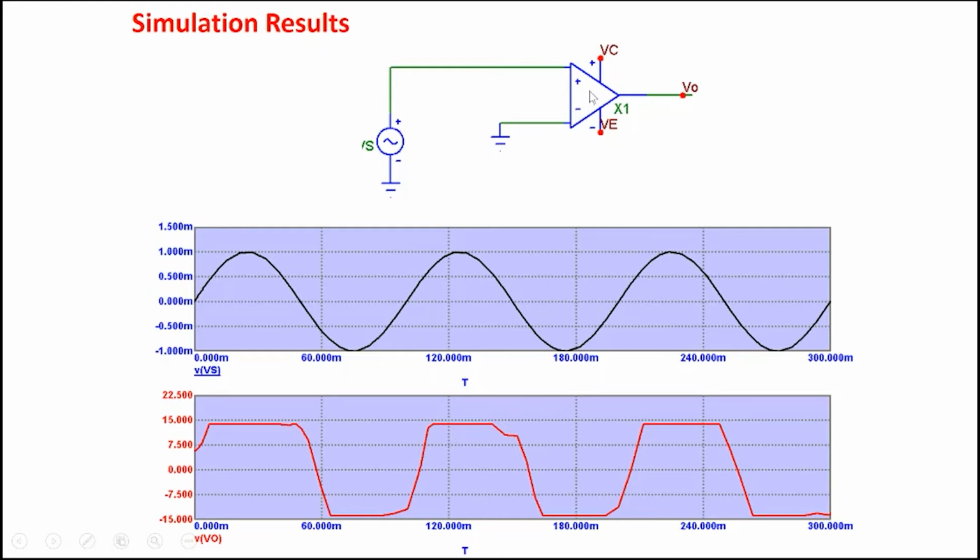Because the gain of this amplifier is so high, 10 to the power 5, if I want to amplify a signal, let's say even 1 millivolt, sometimes I may have a signal which is 10 millivolt, I cannot directly connect that signal here and get the output that we want, because the op amp will very quickly saturate. That's the reason why we said in the beginning that this amplifier is a partially complete amplifier. You have to add further things in order to use it. You can't simply connect an input and take the output and have things be fine.